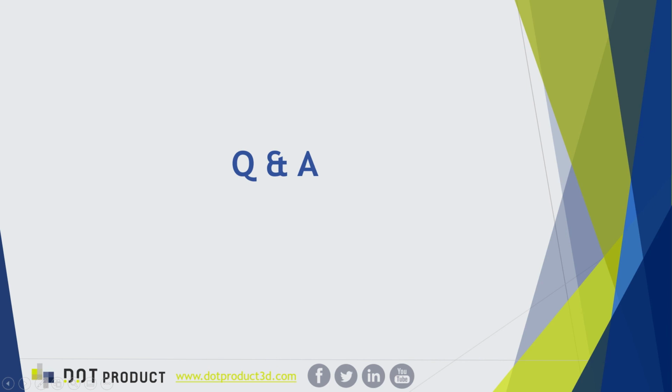Next question here. Are there problems with scanning geometry captures of curved surfaces? In short, no. The more variance, the more geometry, the better. The worst case scenario is a completely empty, completely textureless, flat white wall. That's where you struggle. But if there's anything going on, curvature, even just texture, so color changes, all of that is going to assist you as you move through your scene. So the good news is it's very uncommon that you want to 3D scan a giant empty white wall, because a tape measure would probably have you covered in that scenario. So the more that's going on, the better.